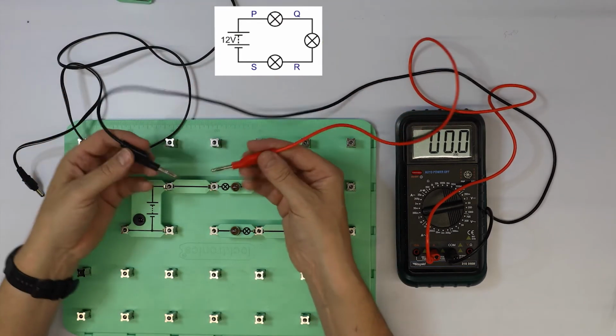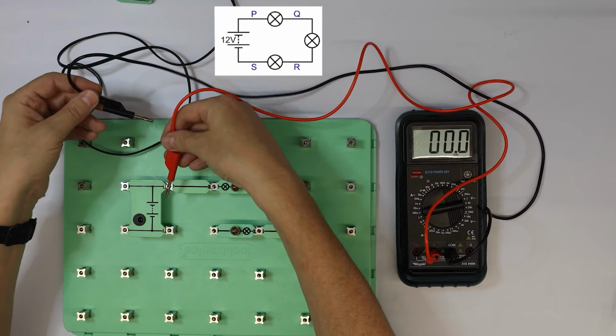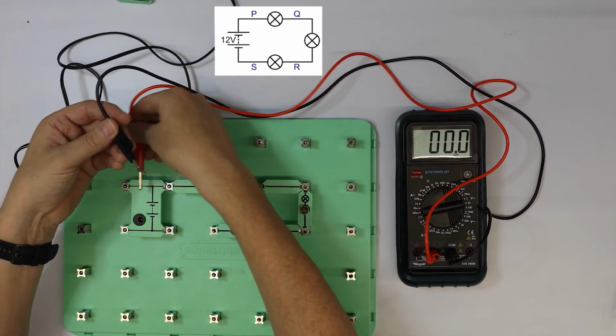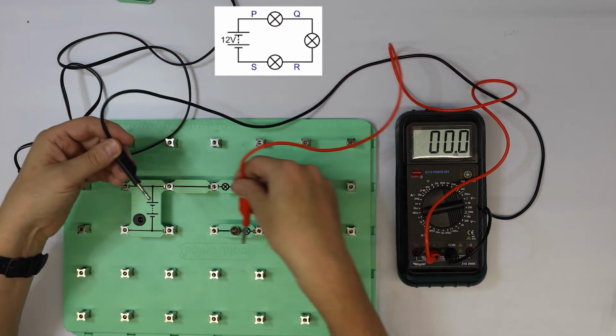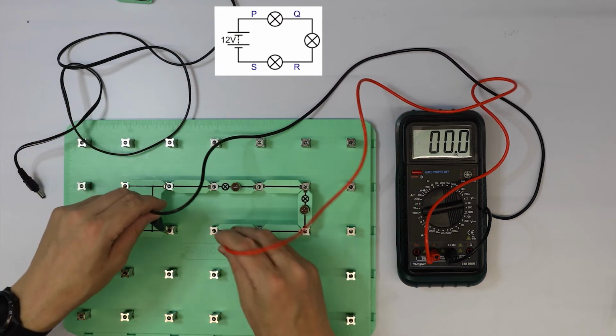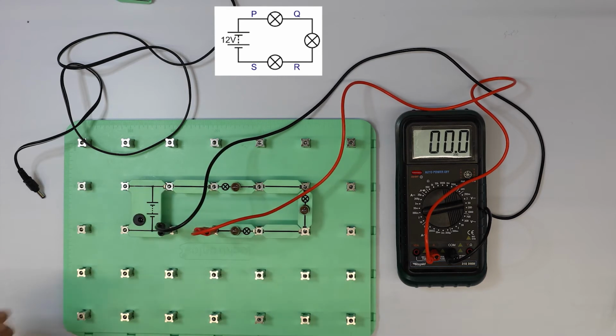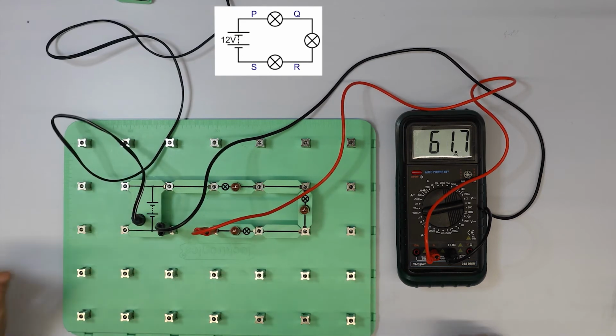Notice that I've actually changed which way round the red and the black leads go. That's because, once again, the red always has to be the positive side of the circuit. So if this is a positive side, it means it actually reverses when we come back here. So the black lead goes on the left now, and the red lead goes on the right in order to get the right value. So if I connect that back up, yeah, once again, 56.6 milliamps for the circuit here.